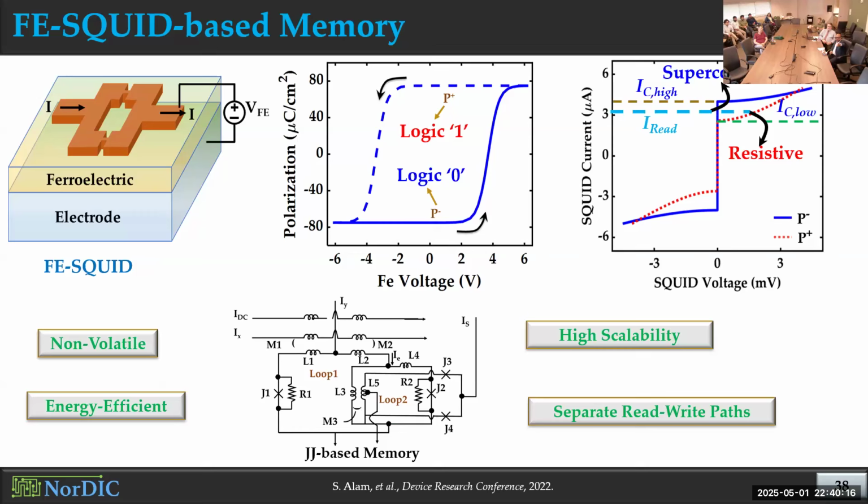So all this hard work to get this one memory cell working, but still volatile. And with this, as I mentioned, the scalability is a major concern because of these inductors and the large cell size. And the highest memory that could be demonstrated experimentally with this Josephson junction technology had a storage capacity of 16 kilobits so far, within a 5 by 5 millimeter square chip. So you see that that's of no use because of the storage capacity that we have. And the major challenge is again these inductors and the large cell area to store 1 bit here.